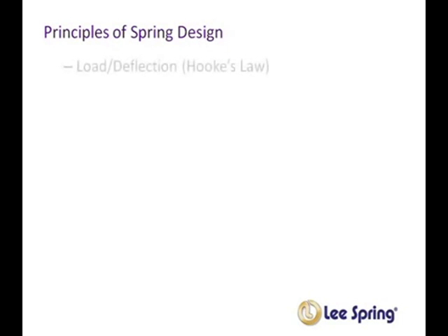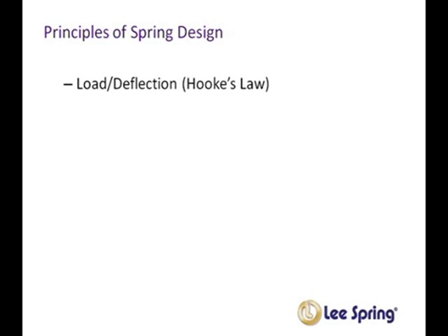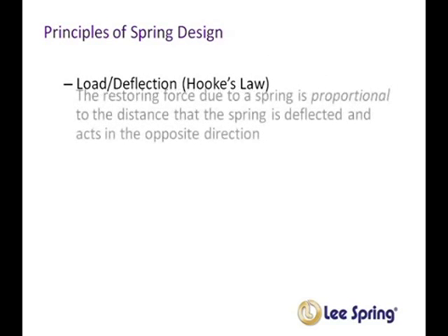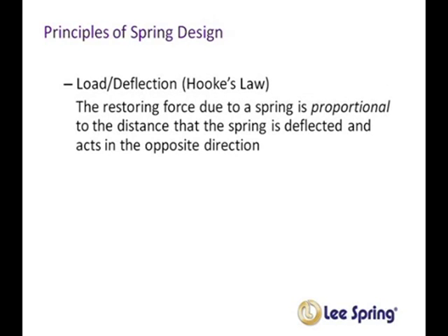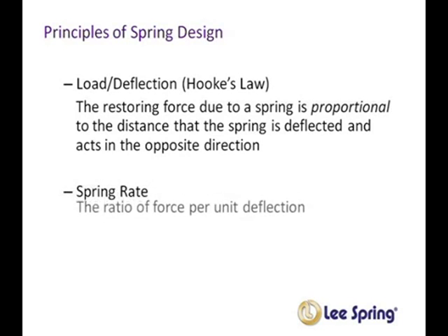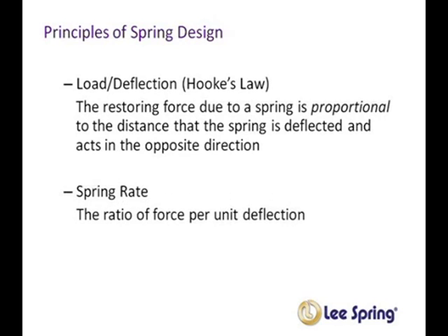Now some basic principles of spring design. There is a principle of spring design known as Hooke's law, which relates to load and deflection. Essentially, Hooke's law states that a restoring force due to a spring is proportional to the distance the spring is deflected and acts in the opposite direction. Another important principle related to spring design is spring rate. The spring rate is the ratio of force per unit of deflection.